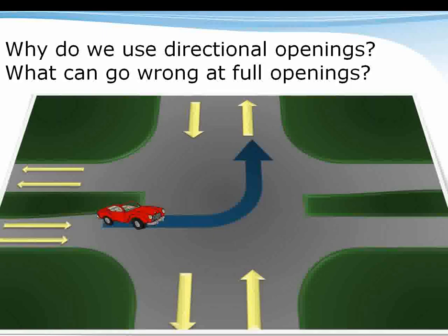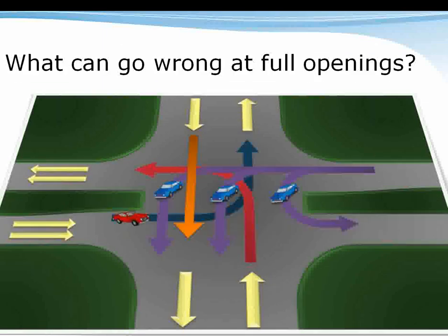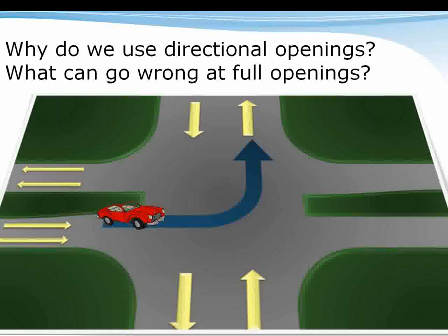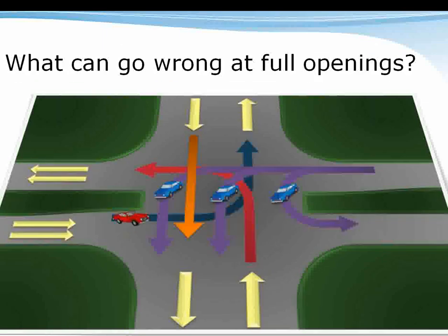Well, what's another advantage of a directional median opening? When you have a full median opening, it was designed to handle just a few cars at a time. What happens in reality is at these unsignalized full openings, you have a lot of vehicles jockeying for position, and all the good work that the designers did on sight distance is thrown away.